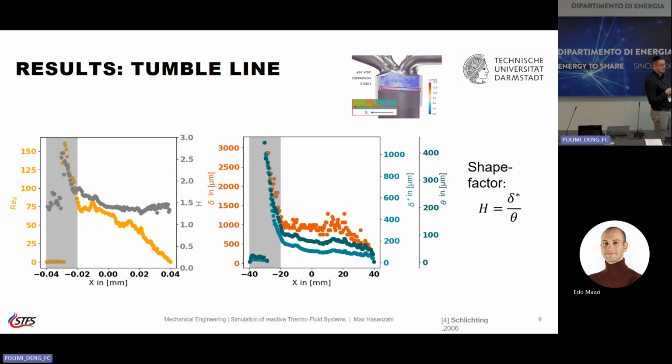What we can see quite clearly is you catch the flow on the right side because of the tumble. And pretty much the boundary layer starts growing. There are some regions where it's decreasing a little bit, and then you have the flow detachment on the right. Notice also you have fairly low Reynolds numbers, so the flow is quite slow.